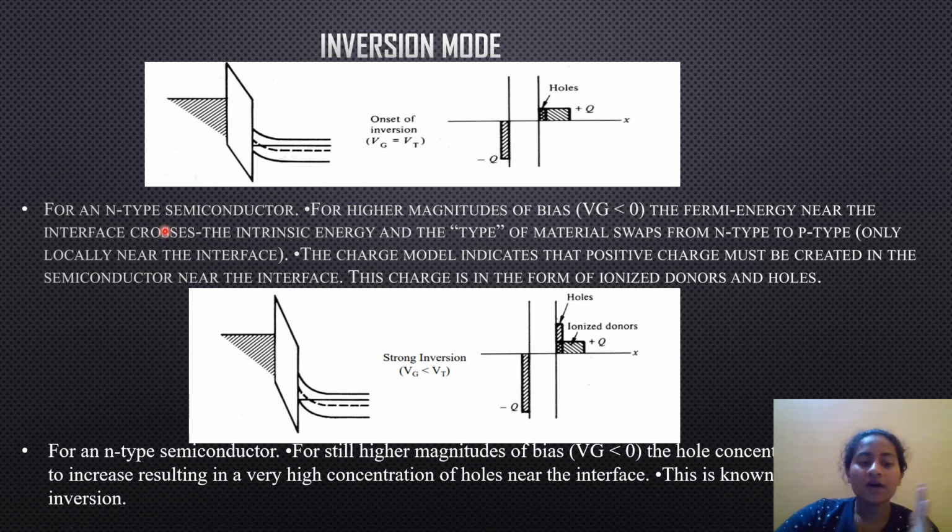That is nothing but the threshold voltage of a MOSFET, as we are discussing the transistor, the MOSFET. So I am explaining the threshold voltage with respect to MOSFET. The threshold voltage of a MOSFET is the value of the gate voltage when the conductive band forms between the transistor's source and drain.